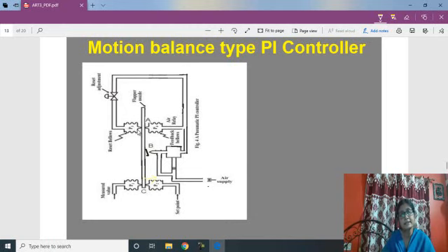Because the signal at these two bellows elements will not change instantaneously. So A behaves as a pivot, and since the measured value exceeds the set value, the motion beam at point C will move towards the right. A acts as a pivot, so B will move towards the nozzle direction. Then the nozzle feedback pressure will rise.